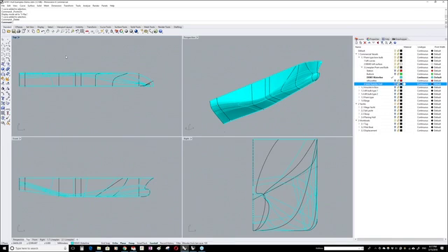For example, I have done a fairing job for a Dutch design office recently, and they use Cadmatic for structure modeling. And then we were also discussing with Cadmatic about several improvements to combine Rhino hull surfaces with Cadmatic. But Gerard, for the MaxSurf example, I've tested it quite a bit at the university in Delft. And the loose loft method surfaces in Rhino and the surfaces made in MaxSurf are, in my opinion, quite compatible. And you can share them. Maybe other types of surfaces get a problem in MaxSurf, but the loose loft surfaces can, in my opinion, be easily transferred.